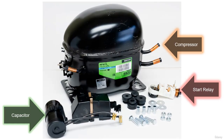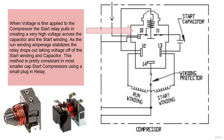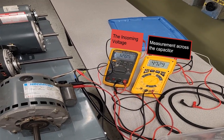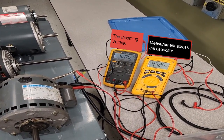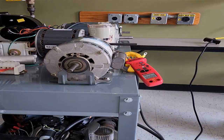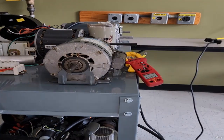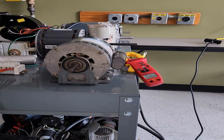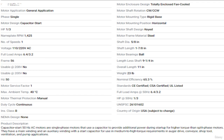In compressors using start capacitors, the start relay is controlled by amperage. It's important to understand that the capacitor in the circuit will temporarily give you a high voltage reading because of its ability to react higher than the applied voltage across the start winding until the switch or relay take them out of the circuit. Cap motors that just sit and hum until you spin them by hand and then they run great typically have a bad capacitor. Troubleshooting a motor will be much easier if you understand all the variables.